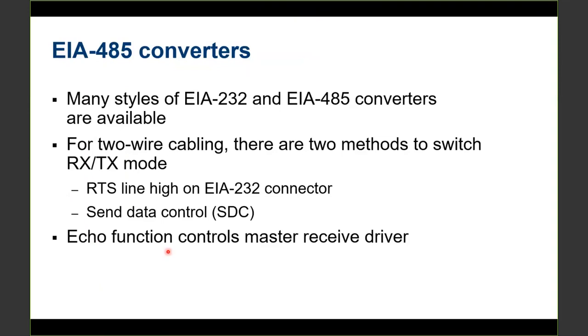That can cause issues sometimes, so depending on the application, you'll want to turn echo on or off. Typically on 4-wire applications, I can turn echo on and it works great. For 2-wire applications, it's not a good idea to have echo in most cases.